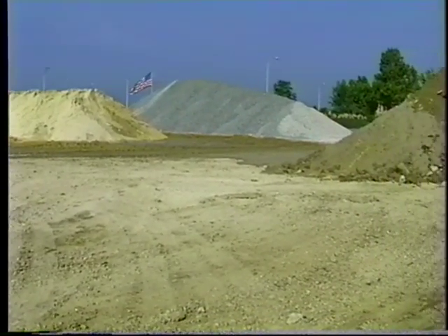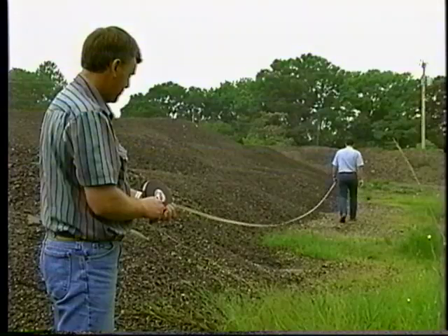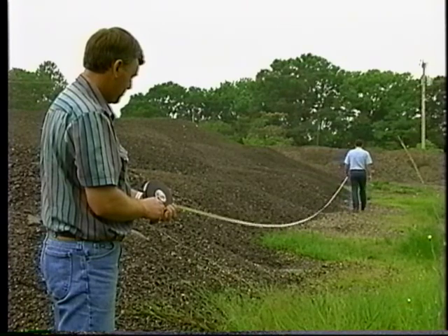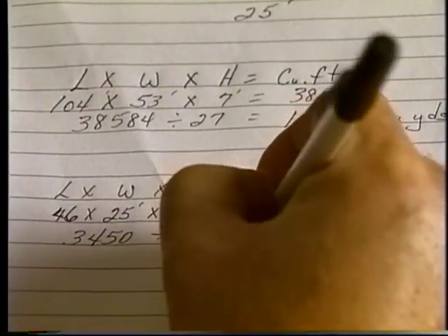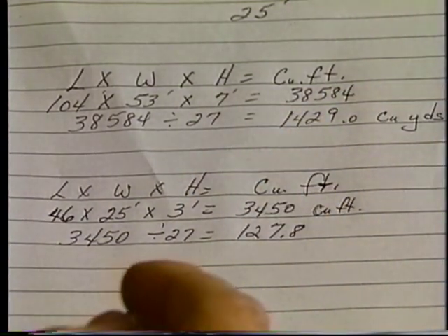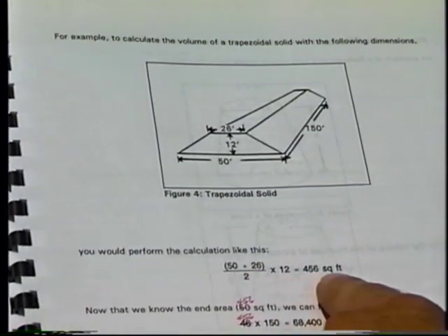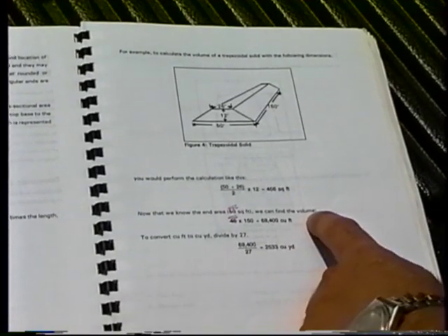Regardless of the type of storage area from which the samples will be taken, you must first determine the volume of the stored material to be sampled. This may involve physically measuring the storage area and calculating its volume. Refer to the Sampling Aggregates, Aggregate Mixtures, and Soils Handbook for more information on performing material volume calculations. Now, let's move on to the procedure for sampling stockpiles.